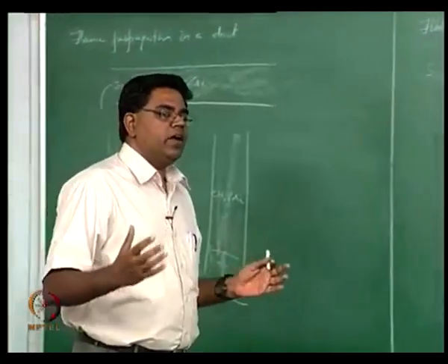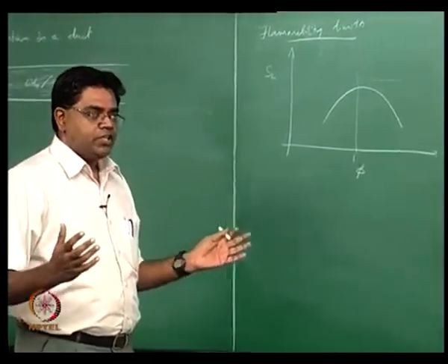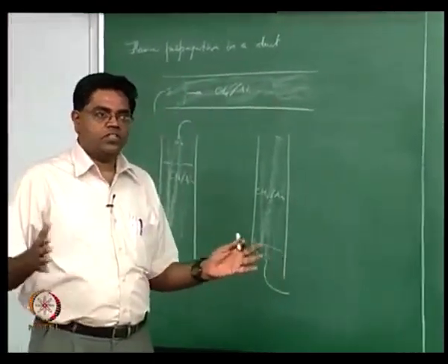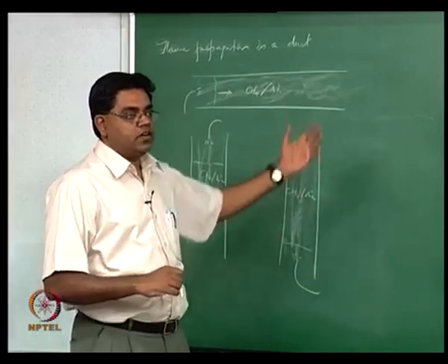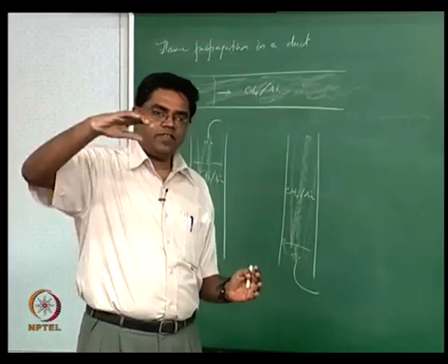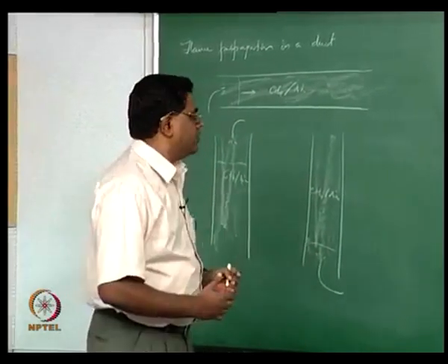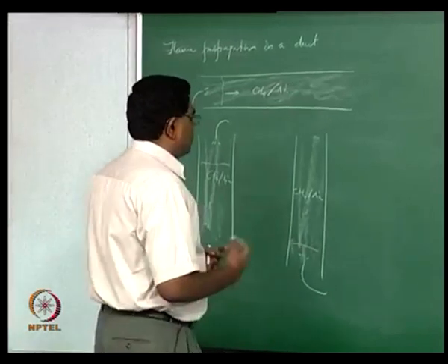There are many apparatus that are used for measuring flame speed, and each of them has its own uncertainties because of additional effects that are not considered typically in the flame speed experiment. For example, in a spherical flame you have a flame curvature effect that's coming into the picture that is altering the flame speed measurement, and so on.